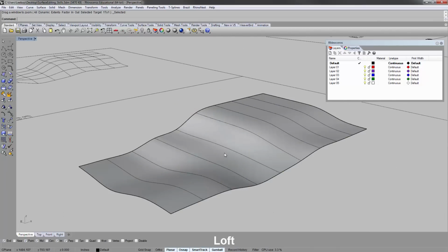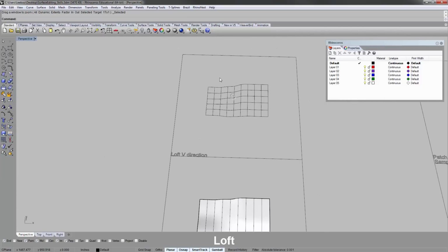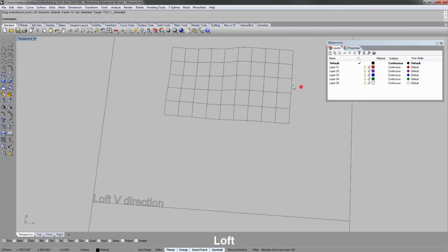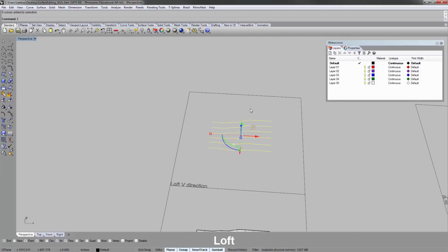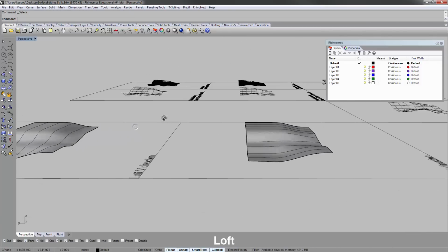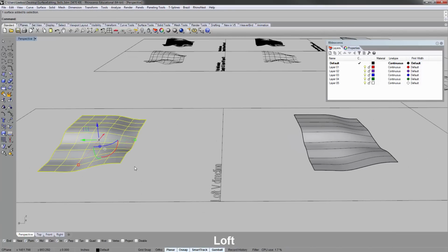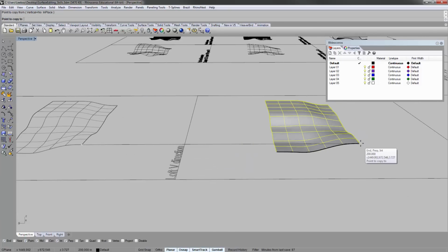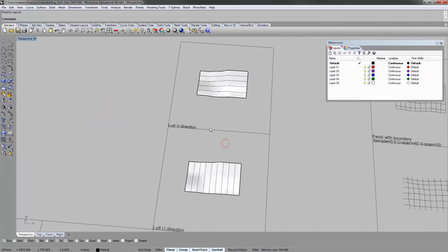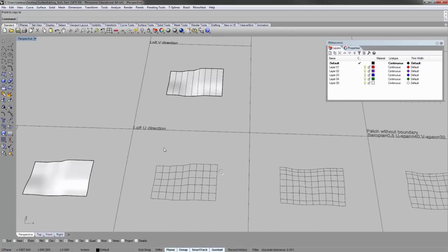Okay, so you'll see the loft just sort of follows your cross-section curves, and if you try it in the other direction, this time deleting everything that's sort of horizontal, all right, and do the same thing, loft. And you can actually sort of compare the surfaces. I think in this case they're actually fairly close when they overlap. Yeah, they look fairly close. You'll run into some situations where, based off of the accuracy of your lofts, sometimes, or the density of your isocurves, these two surfaces actually don't match.